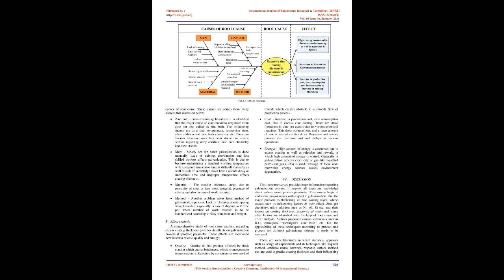Yi Wang, 2018, studied the influence factors such as air pressure, strip velocity, and air knife distance of the air knife, which is the key apparatus to control the coating thickness of zinc in the galvanization process, by using various experimental design methods. Author used response surface method, Taguchi method, and genetic algorithm to optimize coating thickness. Author analyzed robustness by Taguchi method. He stated that air pressure and range of air knife are dispersion factor and position factor respectively. Response surface method and Taguchi method provide fitness function, and genetic algorithm is a good tool that helps to identify the optimal combination of parameters for coating thickness.